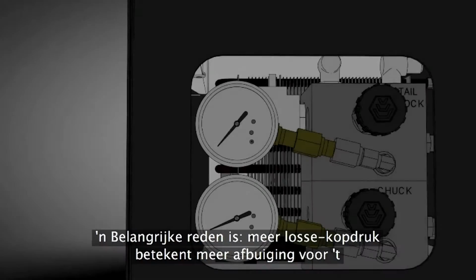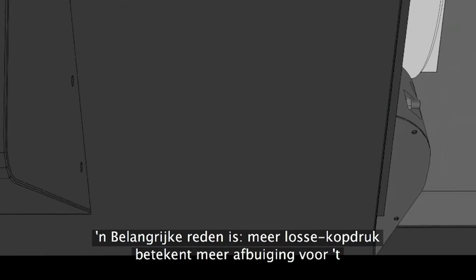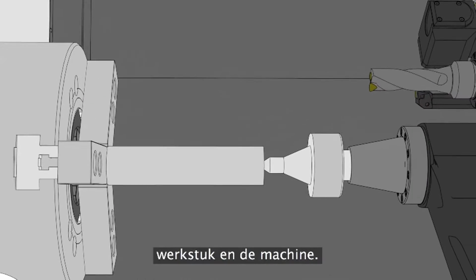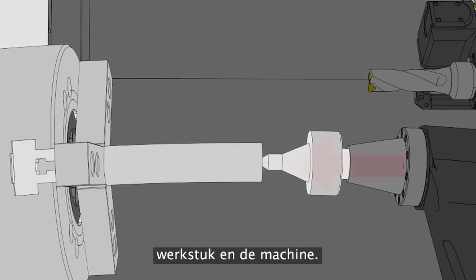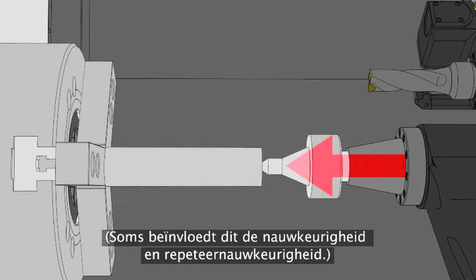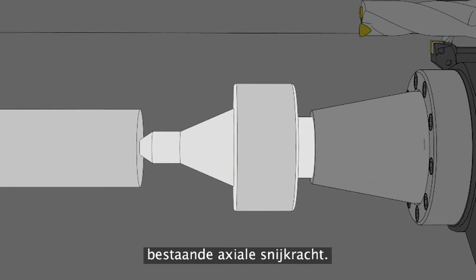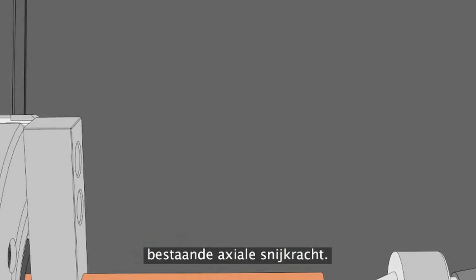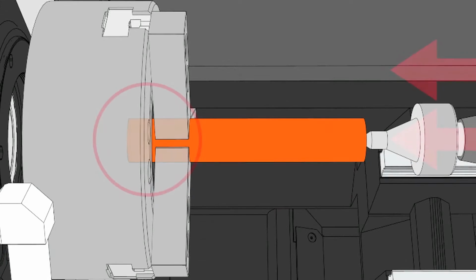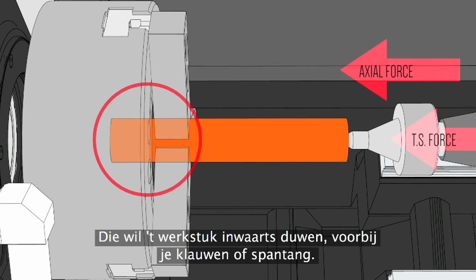Well, one important reason is, as tailstock pressure increases, deflection in the workpiece and in the machine also increases. Sometimes this can affect accuracy and repeatability. You can also increase wear on your live center, and now you're adding more force to the already existing axial cutting forces, which are trying to push the part inward past your jaws or collet.